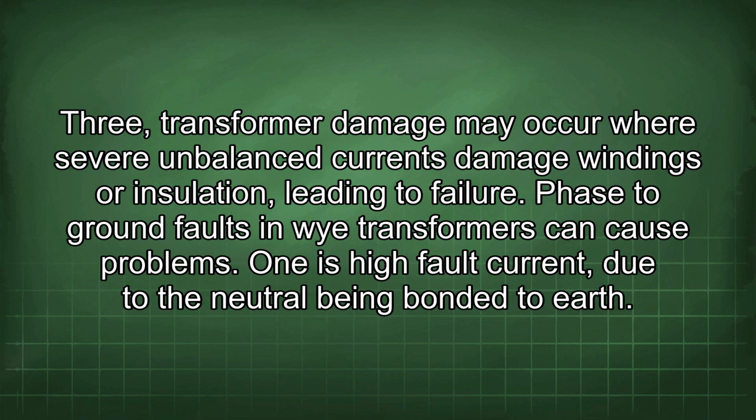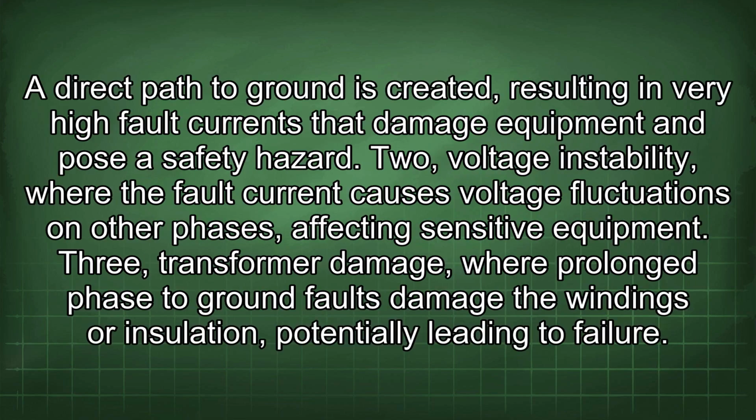Phase-to-ground faults in Y transformers can cause problems. One is high fault current, due to the neutral being bonded to earth. A direct path to ground is created, resulting in very high fault currents that damage equipment and pose a safety hazard. 2. Voltage instability, where the fault current causes voltage fluctuations on other phases affecting sensitive equipment. 3. Transformer damage, where prolonged phase-to-ground faults damage the windings or insulation, potentially leading to failure.